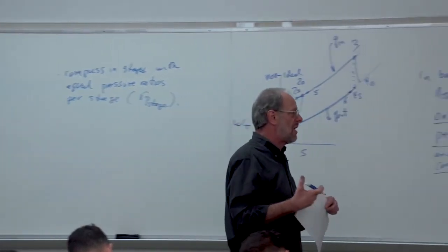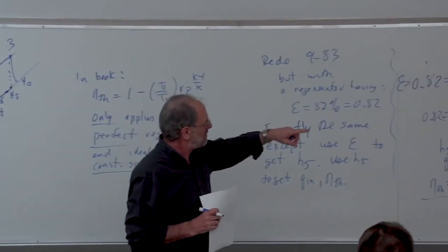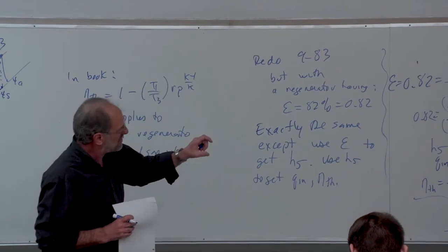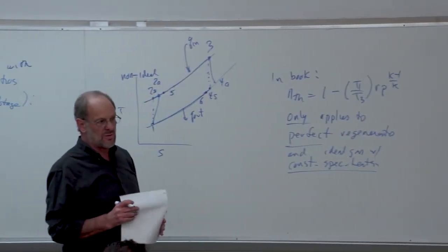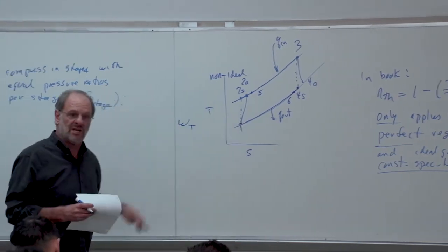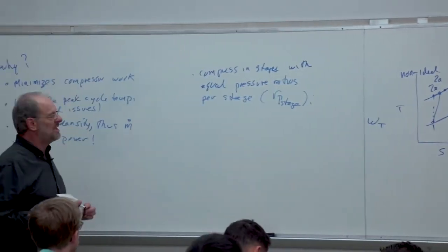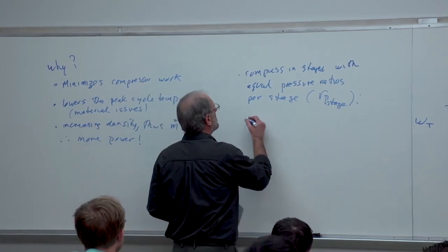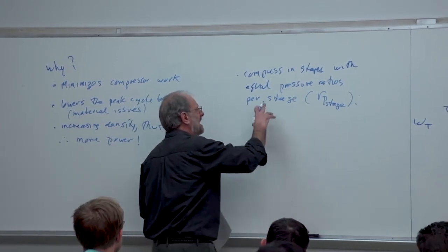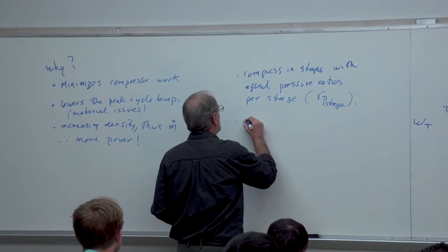The total pressure ratio, RP, is the maximum over the minimum cycle pressure. The pressure ratio per stage is going to be the intermediate pressure over the minimum pressure, or the maximum over the intermediate pressure. But it's definitely going to be in equal stages, in equal ratios. Also, we would note that at the end of this process, we're going to cool.